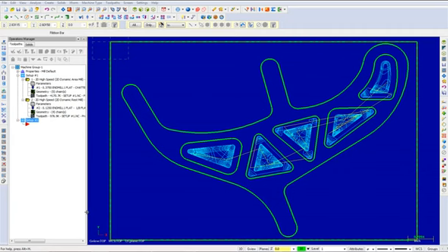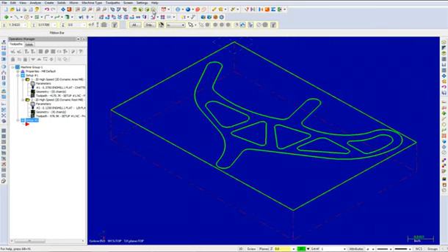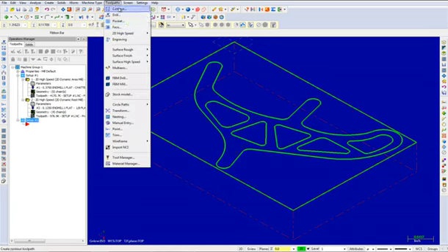First, remove the toolpath display from your screen. To do this, press Alt-T on your keyboard. Also, select the isometric view to view your part more clearly. Select Toolpaths, 2D High Speed, Dynamic Core.